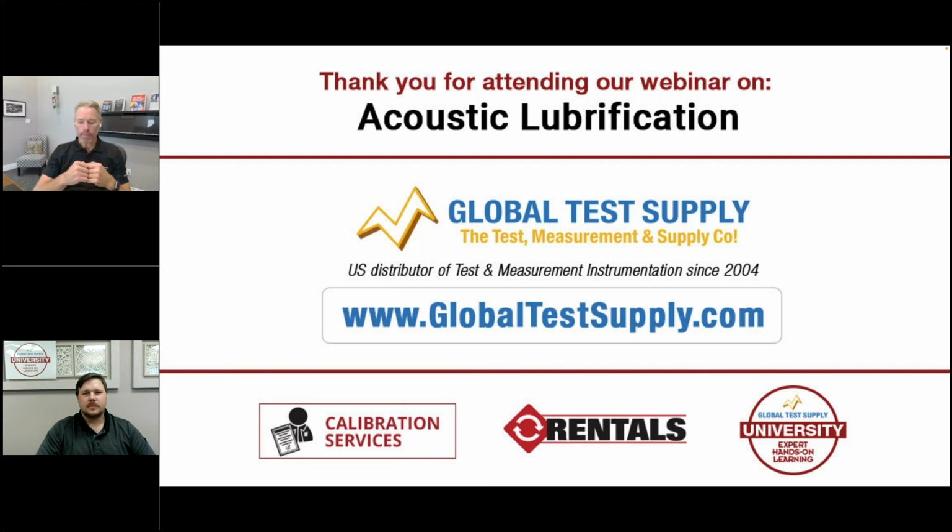So by using ultrasound, we can determine whether or not the interval that we use today is the correct one. And then by looking at all of the historical outcomes of every lubrication task that we ever do, we can go back and use that data to drive our strategy for the future. So if 6 weeks is the right time today, that doesn't mean that 6 weeks from now, it'll still be the right time. So we have to continuously go back and look at our historical results, our outcomes, to drive our strategy on that interval.